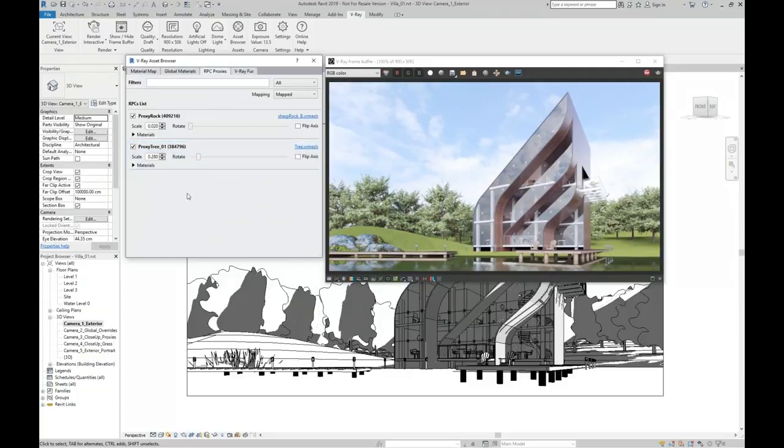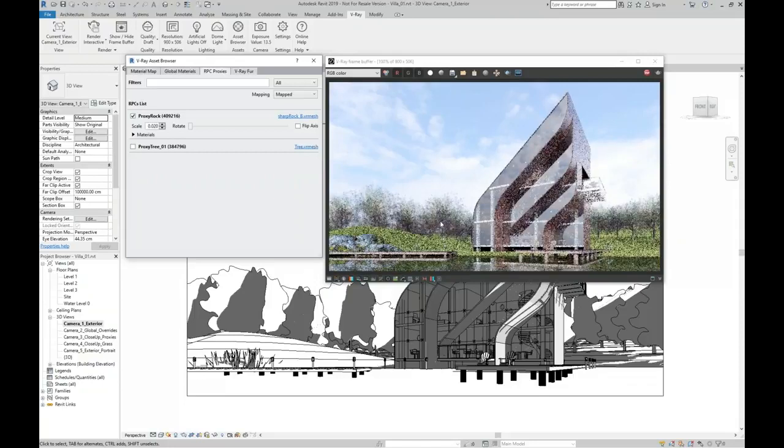Proxies work also the same way like VRmats, just drag and drop. But we will get familiar with the entire workflow during our next episode. So if I turn off the trees, we will see the RPC trees. All of them, all RPCs of that type are overridden with just one proxy, like this.